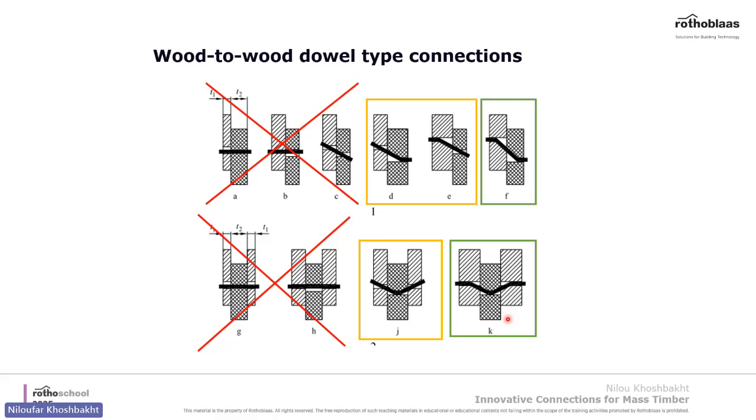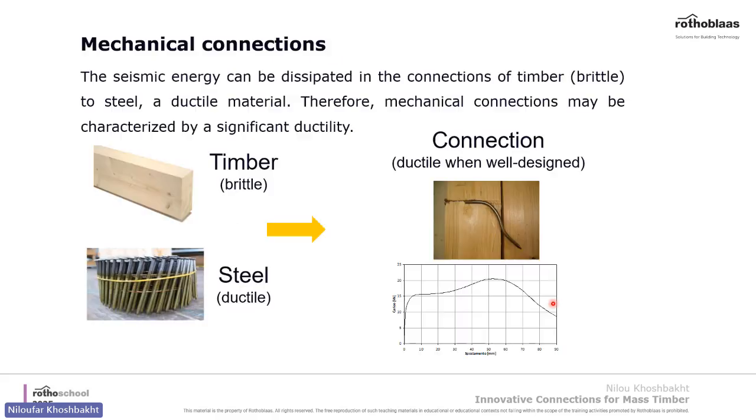So that's why in our connection systems, we want the screw to yield first. You remember the 5 yield modes? We want the screw to yield first, so we want them to be in failure modes 4 and 5 mainly, as you see in this picture.